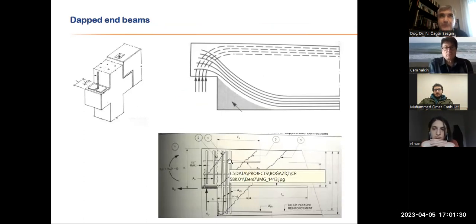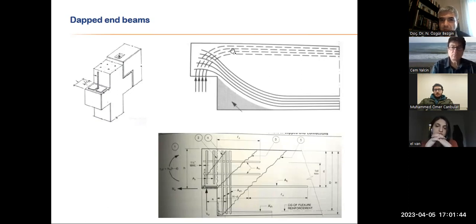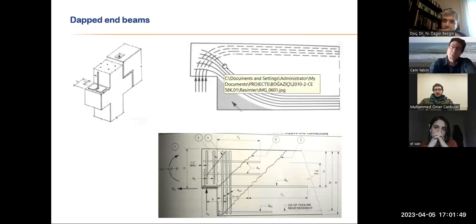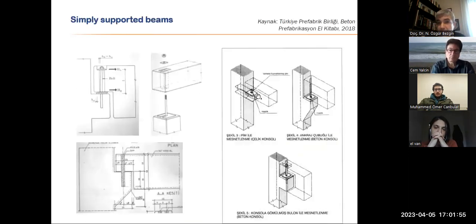So what is reinforced concrete design? We are stitching, basically. In reinforced concrete design, we need to understand how it's going to crack, determine those locations, and stitch through it. That's what we do in reinforced concrete design. And the more we allow ease of flow of stresses, the better, because whenever flow is confined, that's where stress concentrations happen, and that's when our design is compromised. We have to be careful on that.